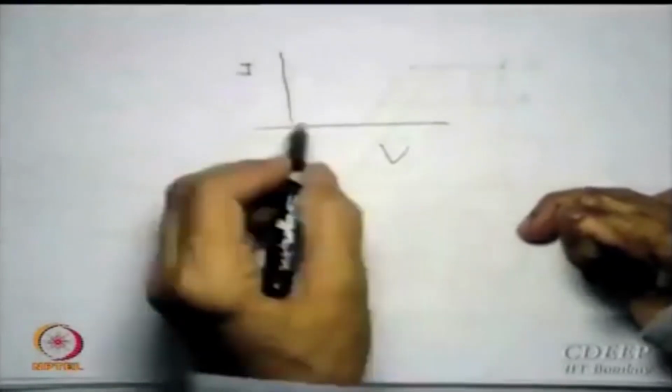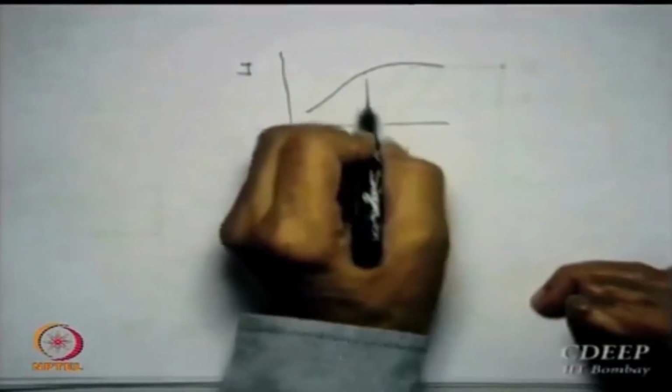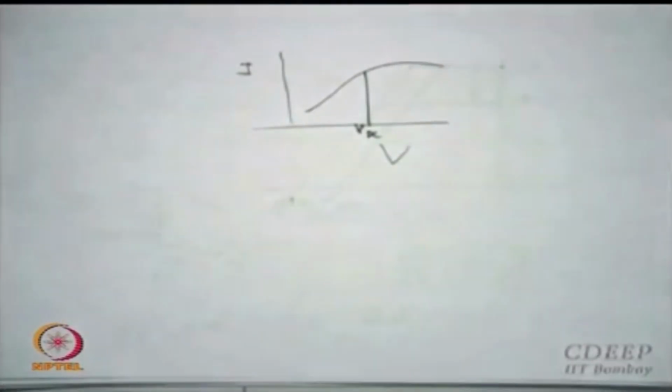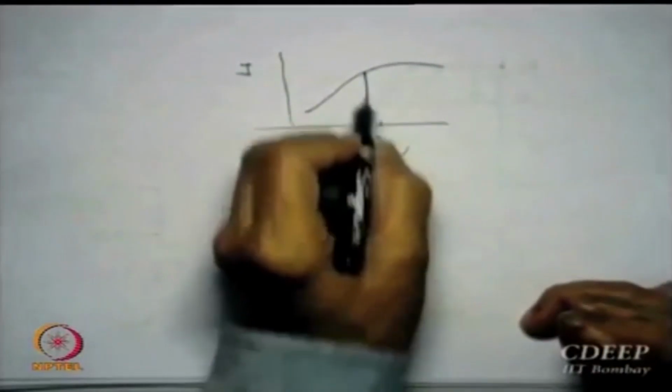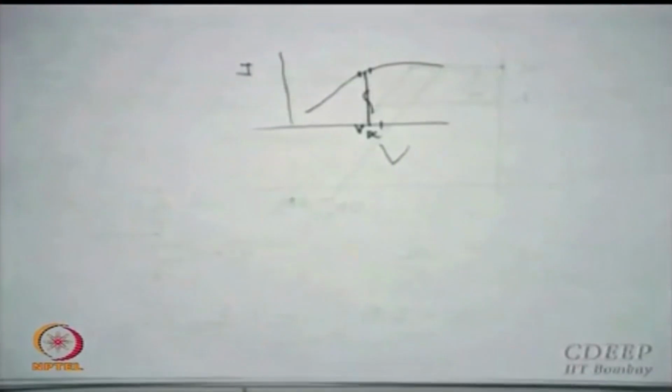Okay, I think you should now go back and do a little more calculation yourself. The way small signal analysis is done in any IV characteristics, let us say this is the characteristic. What we fixed is this DC point, is that clear? And superimpose on this some signal, assuming that the slope here does not change.